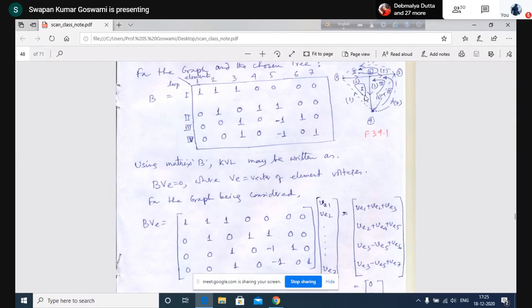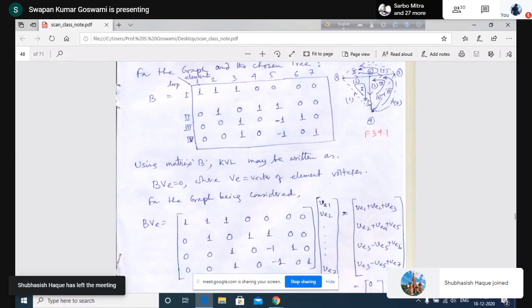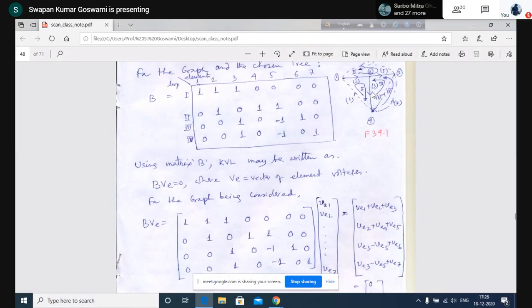You would understand this and try to verify it, because previously, if you write the loop current in this direction and this loop current in this direction, then through this impedance the currents are in the opposite direction. That's why the common impedance of two loops, the mutual impedance between two loops, appeared as a negative impedance. Now, because of this type of loop current selection along with the direction of the loop current, through a common impedance all the loop currents are in the same direction. So obviously the mutual impedance will not be a negative impedance for these loops.